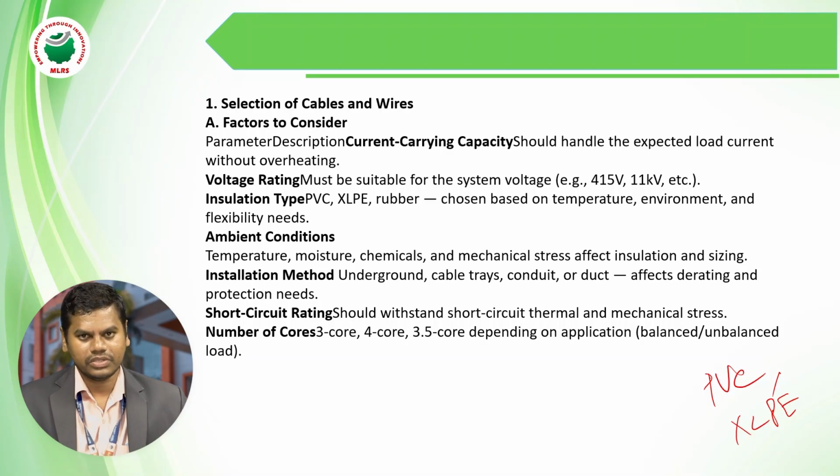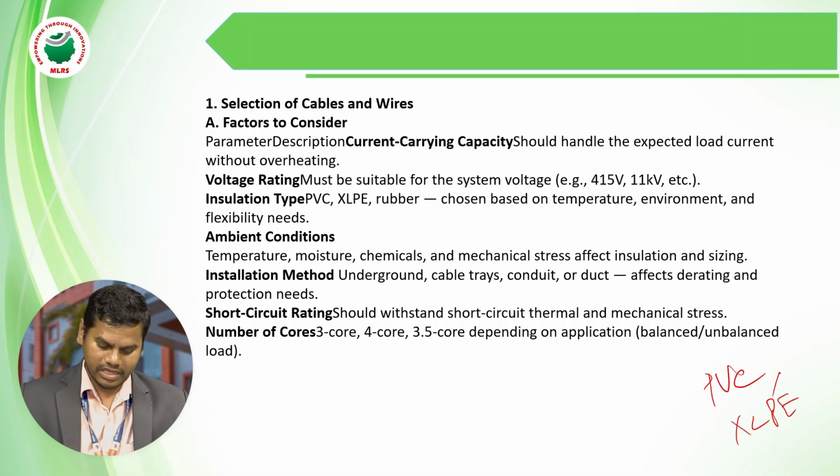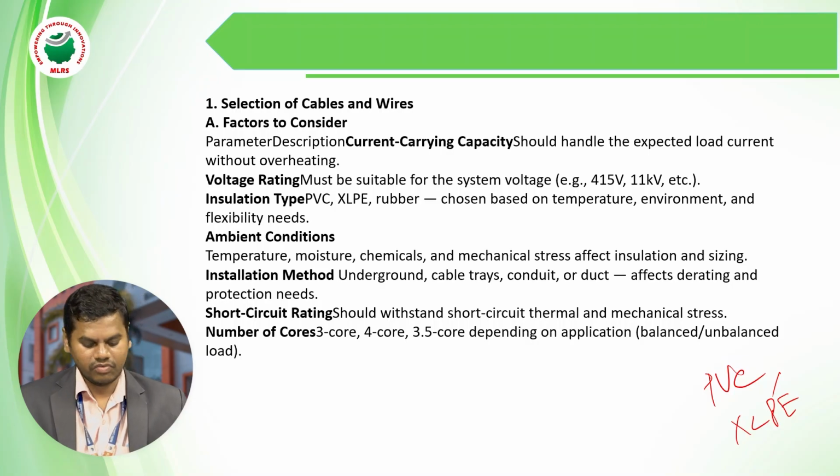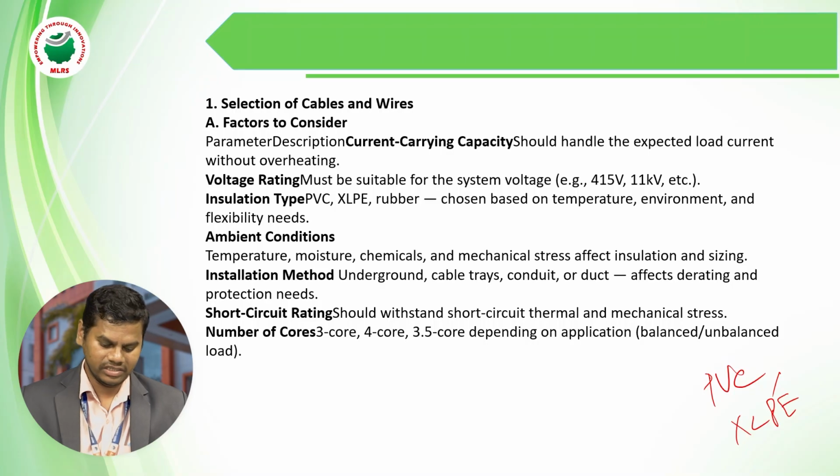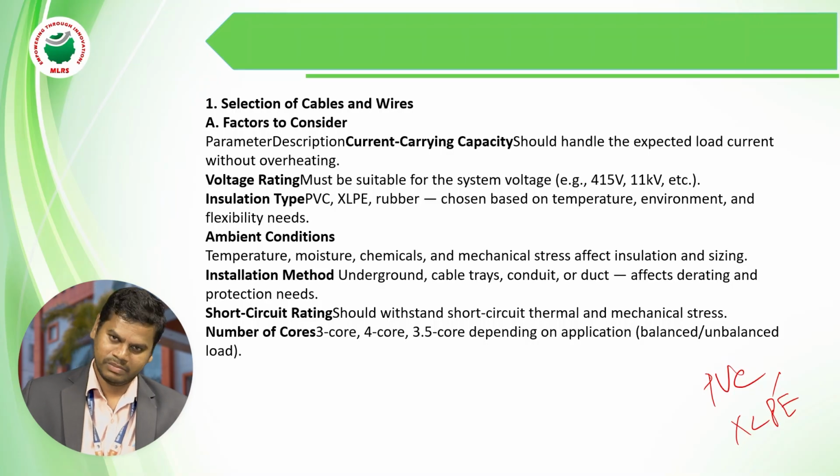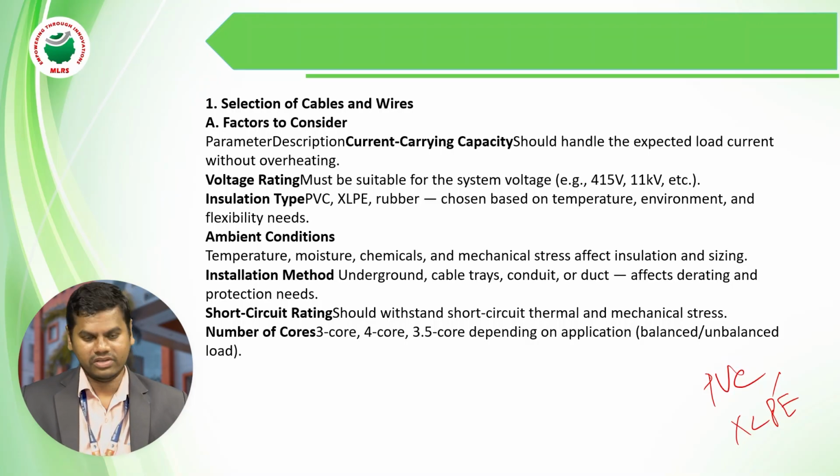How to select the cables and wires? What are the factors considered here? Current carrying capacity, voltage rating, insulation type, installation method, ambient condition, and last but one, short circuit rating, and the last one is the number of cores. So these are the selection of cables and wires.